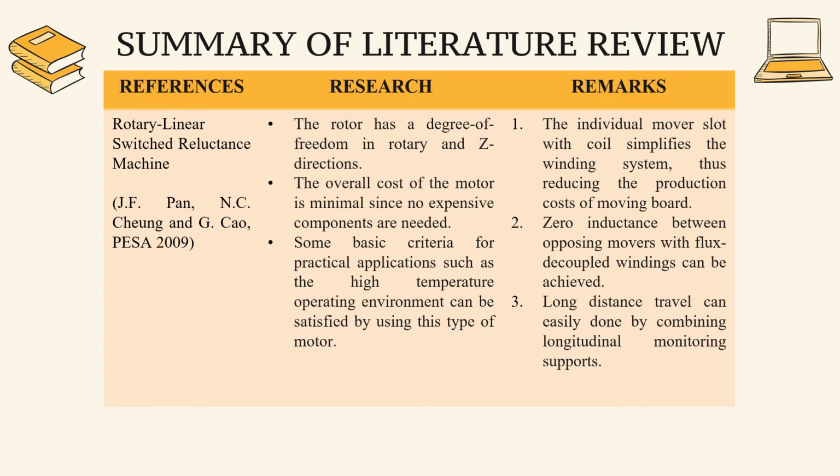Some basic criteria for practical applications, such as the high temperature operating environment, can be satisfied by using this type of motor. The gain is that the individual mover slot with coils simplifies the winding system, thus reducing the production cost of the moving board. Zero mutual inductance between opposing movers with flux decoupled windings can be achieved, and long distance travel can easily be done by combining longitudinal moving support.